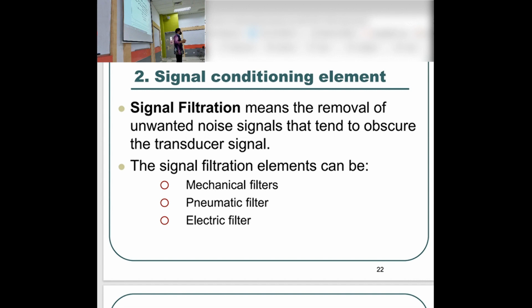But for optical sensors, 100 sensors can use only one DAQ, one data acquisition. In fact, it can be used for 1,000 sensors, because light contains infinite numbers of wavelengths. It depends on how many wavelengths we choose. In the wavelength, a lot of information can be transferred. So each sensor gets one piece of information. That's why they use optical for Unifi or internet, because optical can transfer a lot of information.